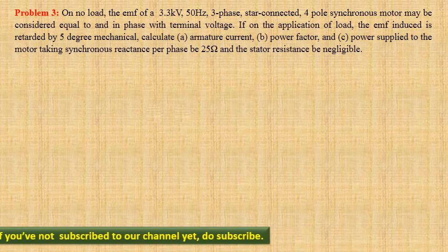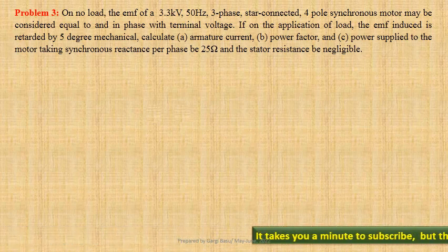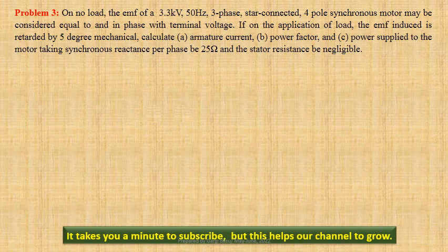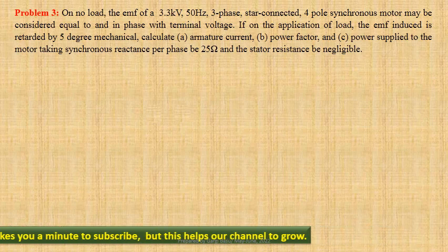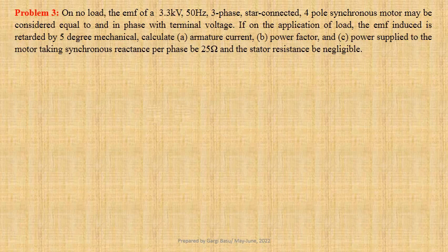If on the application of load, the EMF induced is retarded by 5-degree mechanical, we have to calculate armature current, power factor, and power supplied to the motor, taking synchronous reactance per phase to be 25 ohm and the stator resistance negligible. Let us first write down the given data.